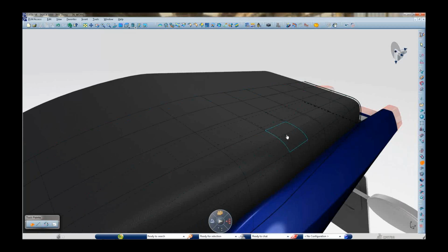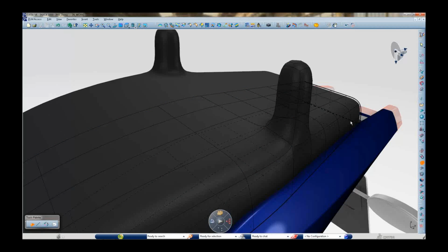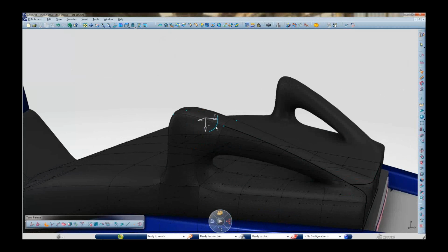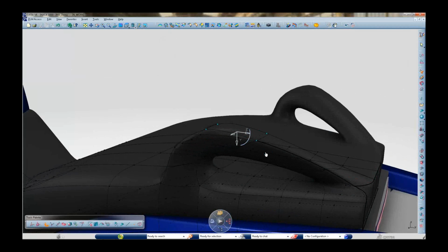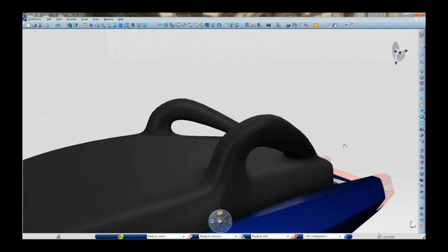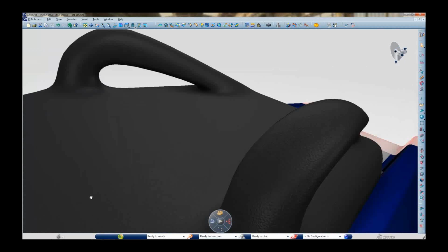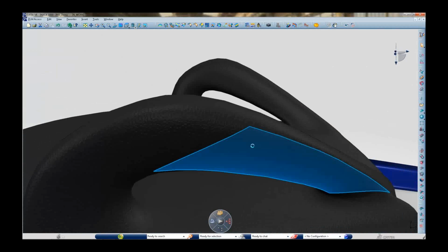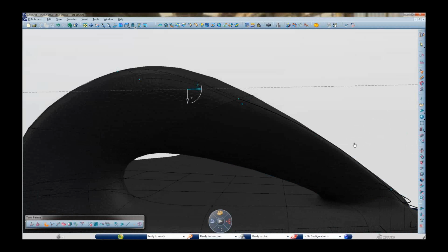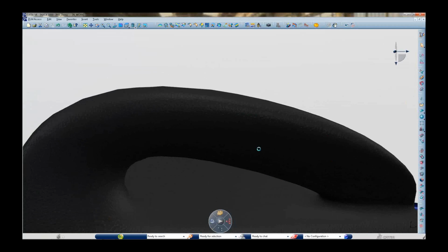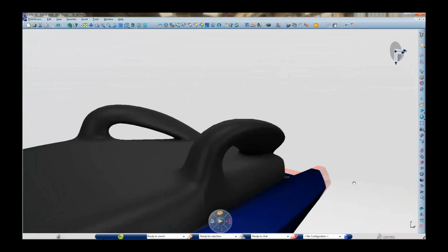So then we will take this face and we just do an extraction, and you see automatically the symmetry updating. And you see that it always maintains a G2 continuity between all the faces. And just by connecting two faces, again, it will automatically connect in G2 all the surfaces, all the patches. So it's a very creative tool, an easy to use tool, an easy ideation and concept modeling exploration tool with a pretty high quality of surface at the end.